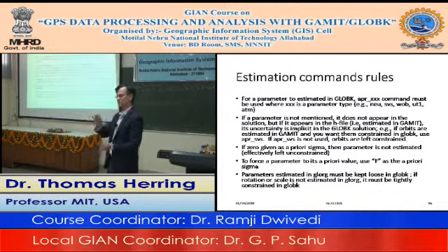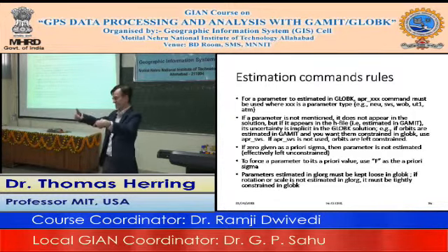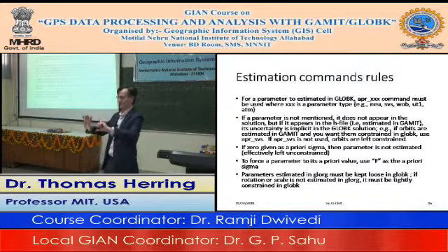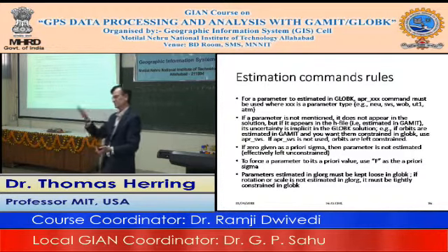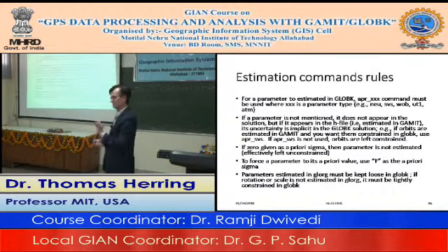That's because of the difference between them. In Kalman filters, you can't start with infinite variance, which implies 0 normal equations. You have to start with something finite. But you can start with 0 variance, which would imply infinite normal equations, and you can't do that in least squares. It's because they're inverses of each other. That's why this f doesn't translate into a tiny little a priori sigma. It translates into 0, and it is actually forced to fix to that value.